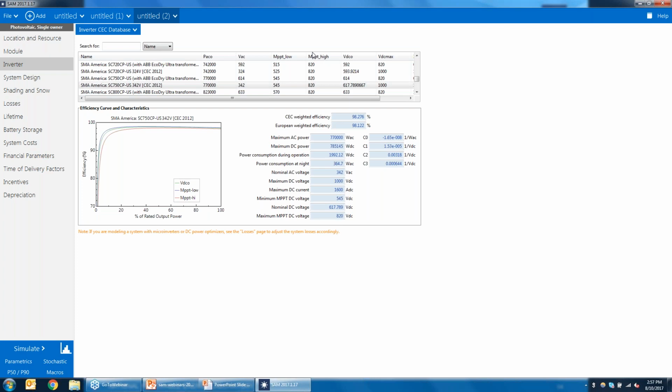And as Steve pointed out silently over here on the end of that question being asked, probably the best way to do that would actually be to use SAM's built-in scripting language, LK, to write a simple script that runs that type of analysis. In scripting, you could set a maximum land area and check against that maximum for each system size. That would allow you to enforce certain conditions and then loop through several different system sizes and ground coverage ratios to find what the optimal would be.